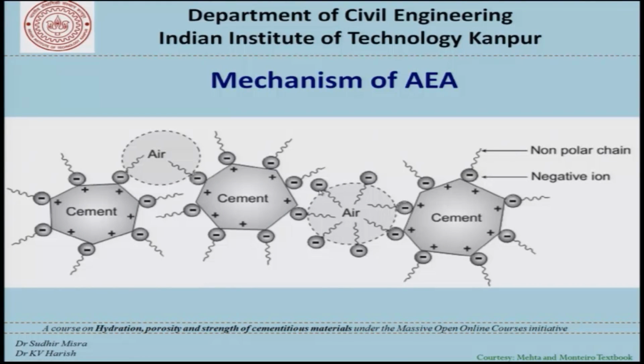Now, many particles surround the cement, and the non-polar chains of the individual particles of the air entraining agent club together and form an air bubble.